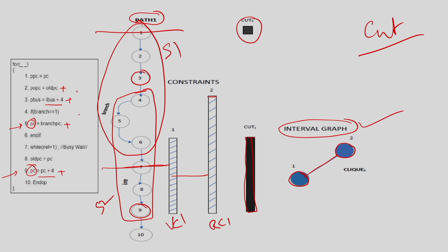Okay. And what is my objective? My objective is to identify the minimum number of carts that satisfy all my constraints, and that can be done using the clique partitioning problem. A clique is a complete subgraph. So, you identify the complete subgraphs in this constraint graph or interval graph such that all the nodes are covered by one of the complete subgraphs and there is no overlapping.